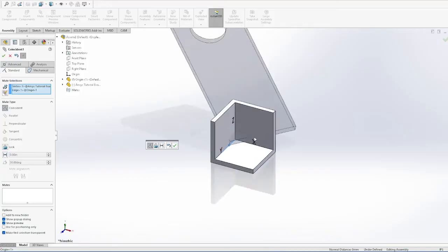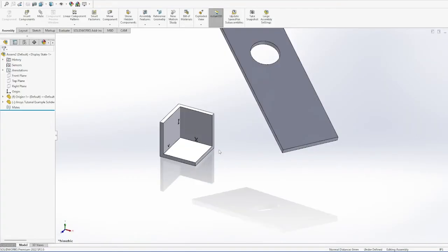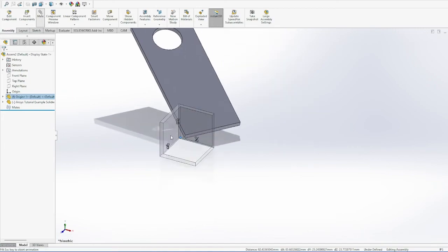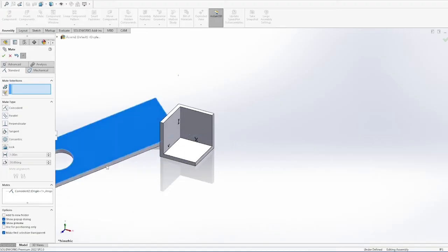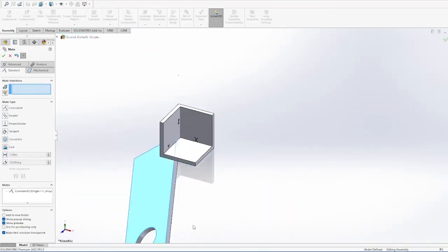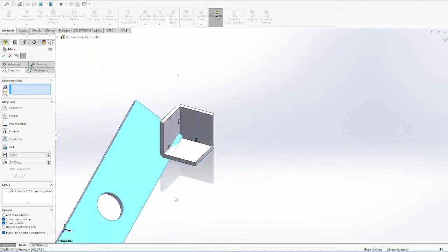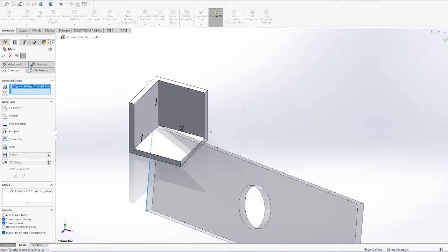So the first thing we're going to do is fix a corner to a corner of the part, which SolidWorks naturally does not want to do. So I'll just choose this corner. And the idea is that we want to basically create a pivot point. If we were to fix the entire bottom side, we would actually have a lot of discontinuities because there's basically just a place that cannot move. There's no way to really create that. So instead we create this little pivot geometry that allows our part to freely move without causing basically any strain or stress on the part as a byproduct of just its existence.